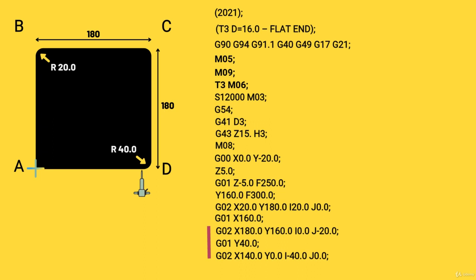Now, all that's left to do is to move the cutter back to the start position and a safe place where we can lift it from the material. So G01 X-20 will bring the cutter 20 mm to the left of our datum position, and that brings the cutter over to where it's shown on this drawing. So now we can lift the cutter away from the component.